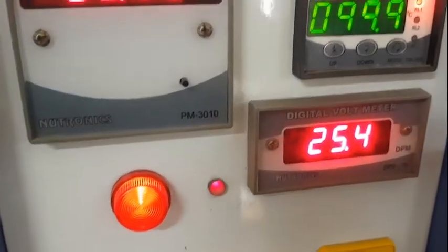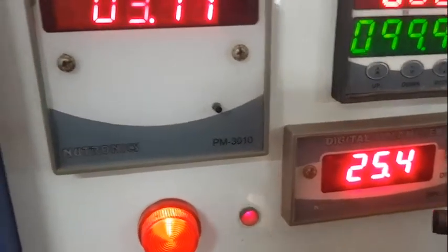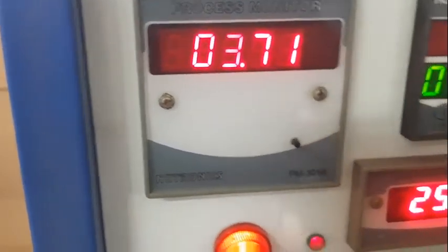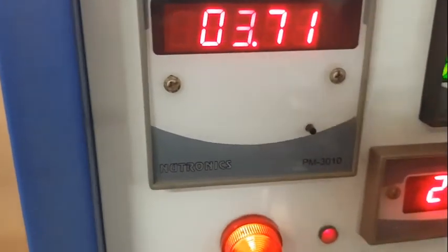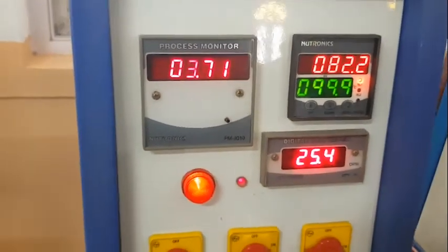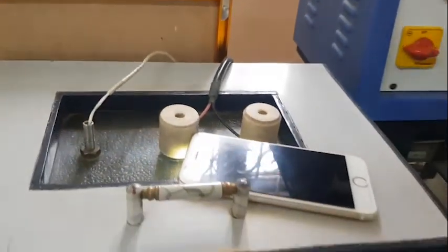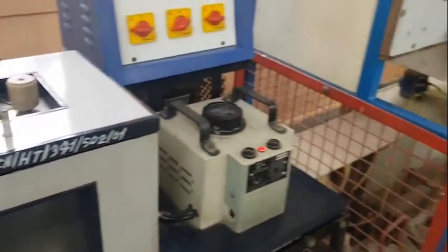You can see here. So what you see here, that whitish flow, is nothing but bubbles, water vapors. Okay. So now at this particular point you can see here the voltage was 25.2, okay, and the current is 3.71. So 25.2 into 3.71, whatever the value of wattage will be there, that watt divided by the area of that nichrome wire, you will get the critical heat flux.